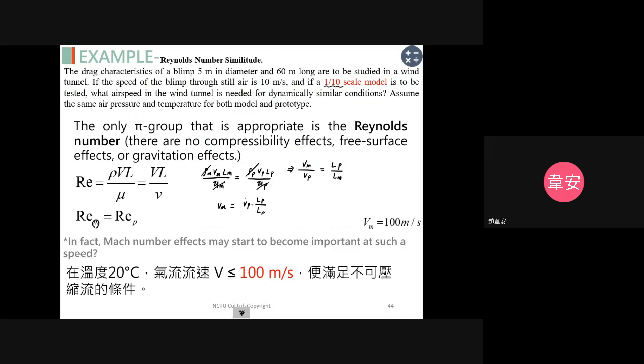As we know, V_p is 10 meters per second, and L_p divided by L_m is 10, given in the information shown here. So finally, the speed in the model should be equal to 100 meters per second.